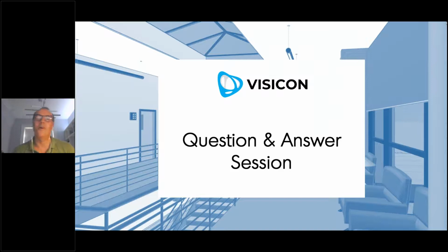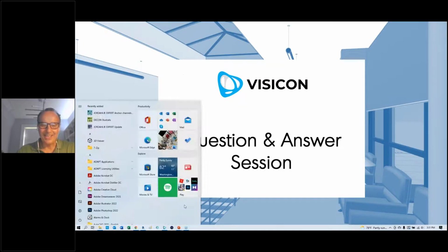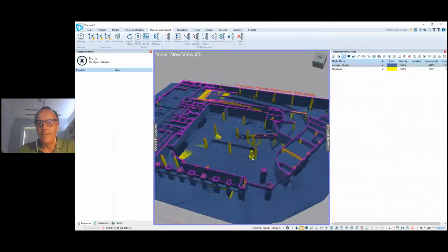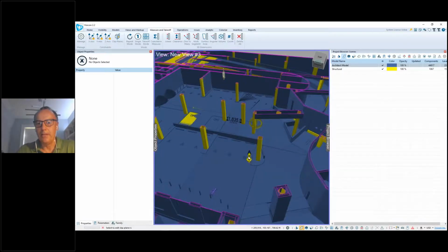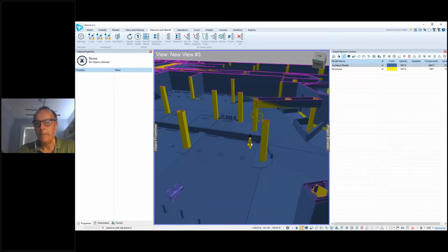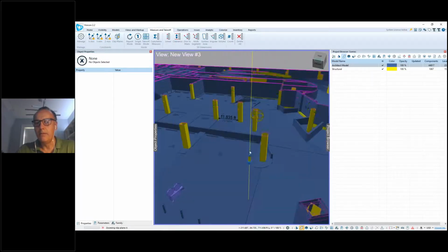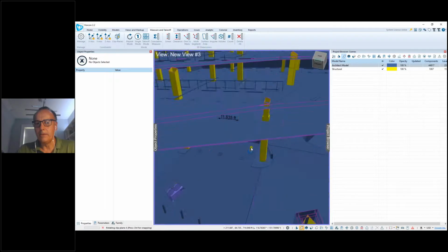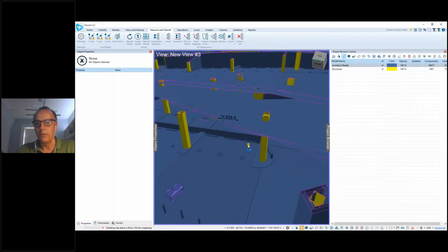So it says, how to stop the rotation of a clip plane if we accidentally touch the end of an arrow? Oh, yes, that is a very good question. Let me demonstrate. What they're referring to is, you see this clip plane widget. The widget has 3 areas. You see how I hover over it? If I click, you see how I've highlighted the shaft? That moves it up and down along its primary axes. If I click the end, you have this rotation right here.